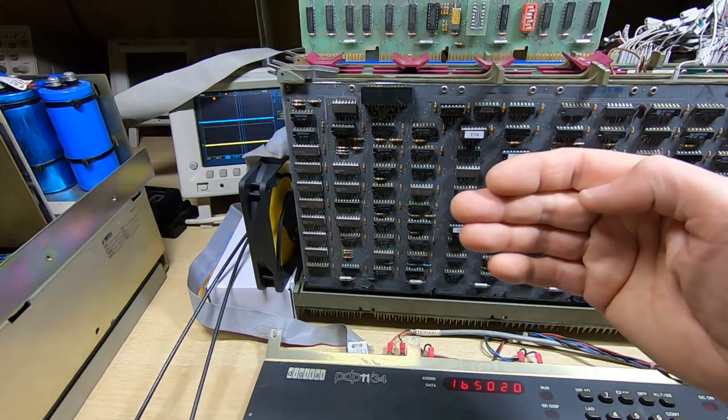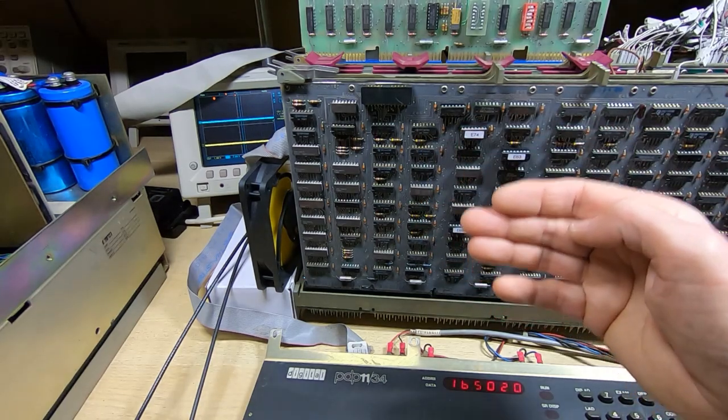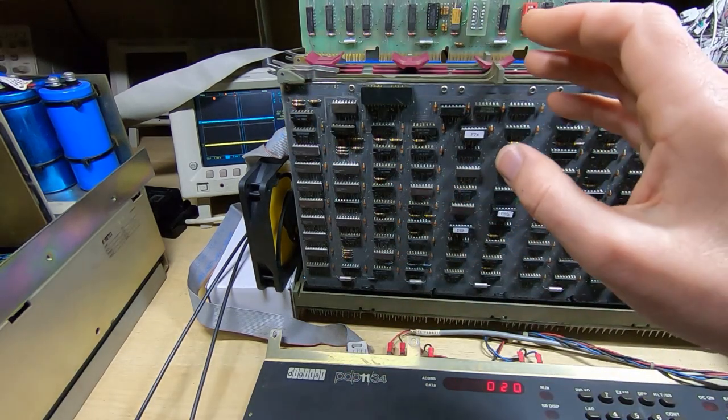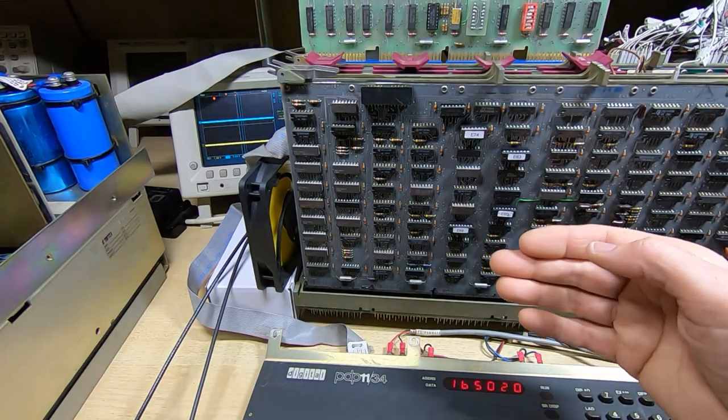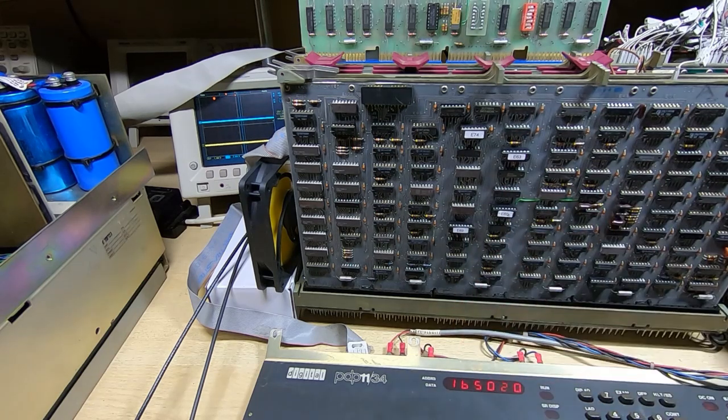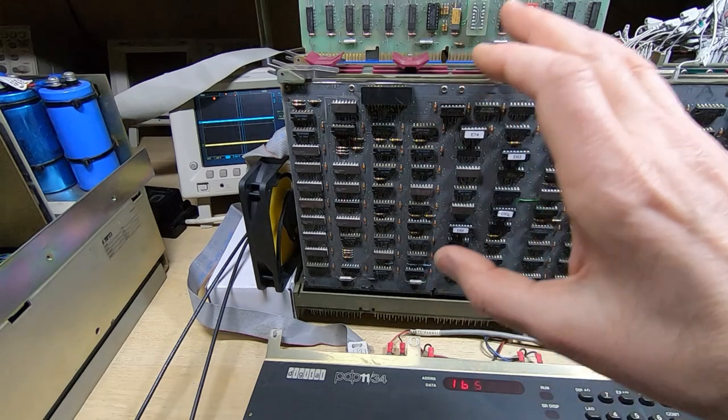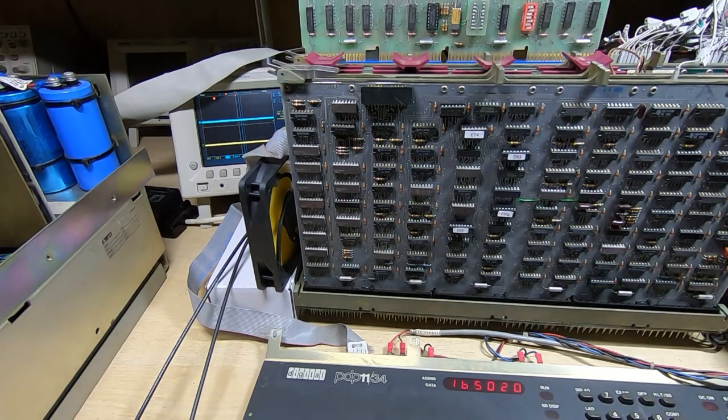It might be used for sending data to the RX02, or it might be used for getting data from the RX02, and the software that drives it has to keep track of the state machine and make sure it's driven properly. And in theory it's meant to guarantee that you don't corrupt the data on your floppy disk.